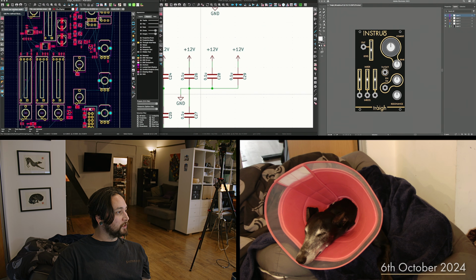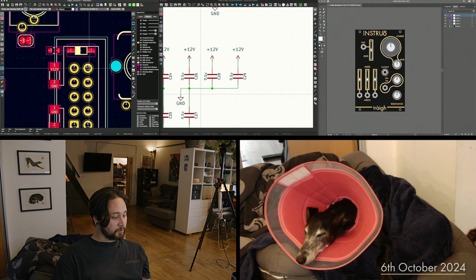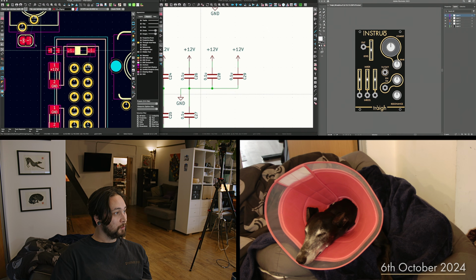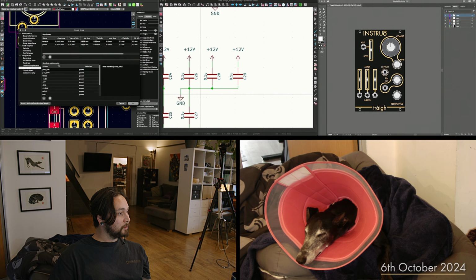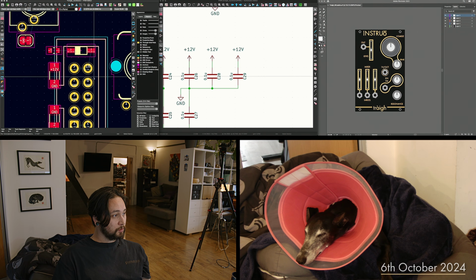this is the control section here. So this is where I use net class width. I'm going to add a couple of extras. So I'm going to go nice big thick traces from here. So this will be the 0.35 track width. But if I add some extras, find sizes, 0.35, let's go 0.5, why not? Then I can select if I'm locking to something.